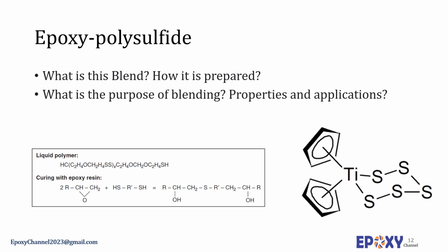The epoxy polysulfide adhesive is usually supplied as a 2-part flowable paste that cures to a rubbery solid at room temperature. These systems can be heavily filled without adversely affecting their properties. Epoxy sulfides are often used in applications requiring a high degree of elongation. These adhesives are generally used to bond concrete in floors, roadways, and airport runways. Other principal uses include sealing applications, bonding of glass, potting, and bonding of rubber to metal.